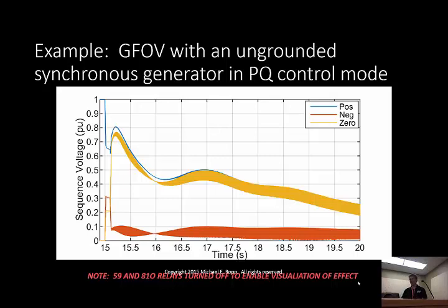A lot of that's not seen in this plot. Hopefully you can also see the very dim red text that's across the bottom of your screen. There are under over voltage and under over frequency relays on this generator that have all been turned off for this specific case. And the reason we did that is so that you can actually see the transient, right? In reality, this generator would have popped off, I'm trying to remember exactly where, maybe about 15.6 or something like that. But it would have gone out on under frequency way, way earlier than what is shown on this plot. But so that you could see the entire transient behavior, we just turned those relays off. Bear in mind that this generator would have tripped a lot faster.